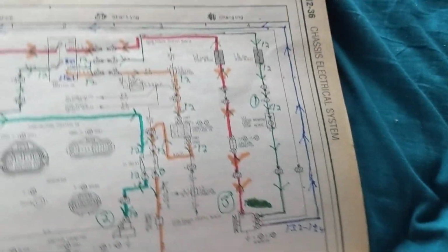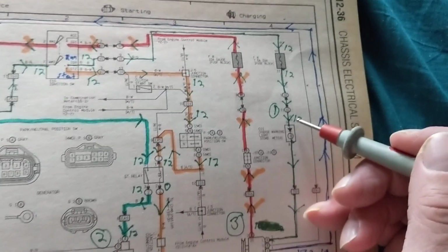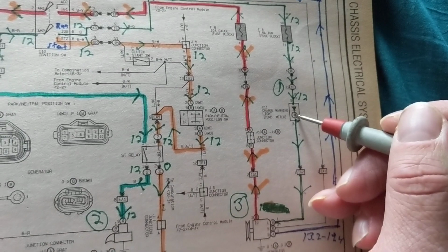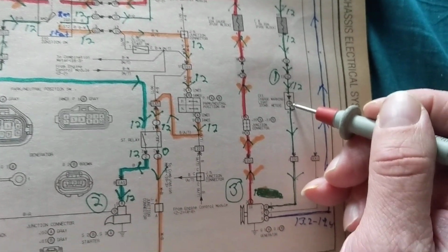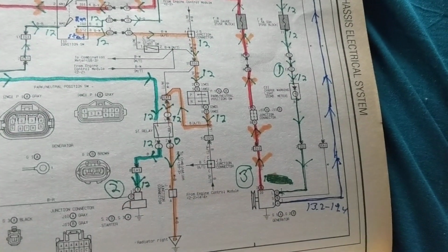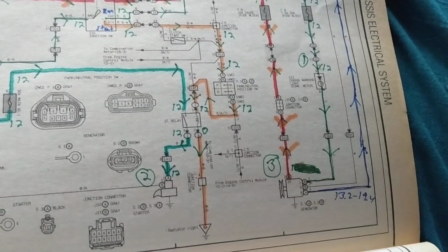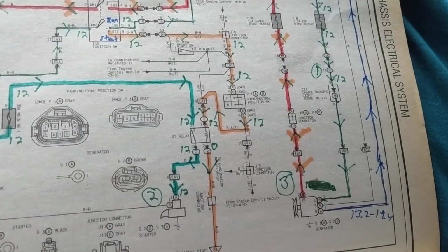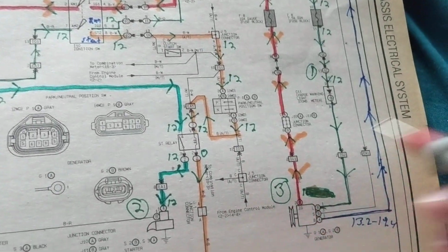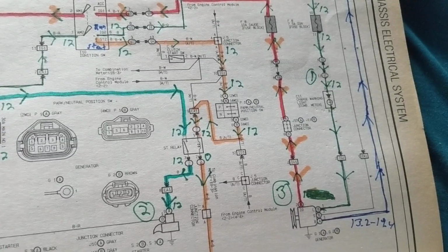So now, what's the purpose of this? You see this bulb is turned on when your charging system has not been activated enough. And that's going to be first in the run position, obviously. Because why? Your engine is not cranking. If your engine is not cranking, the alternator is not working. So, do we expect this to happen? Yes, this should happen. We should see the light go on when in the run position.